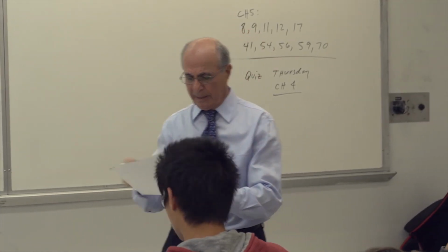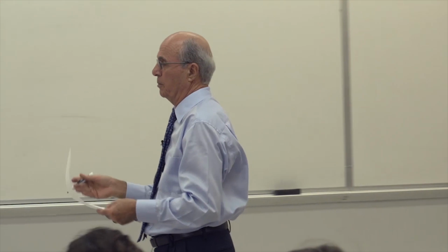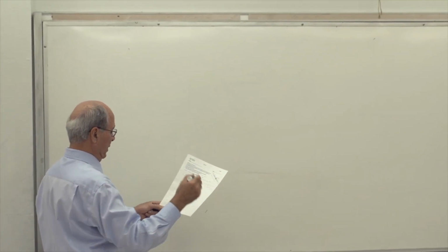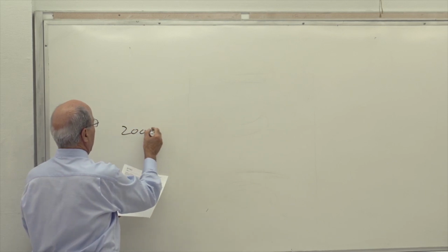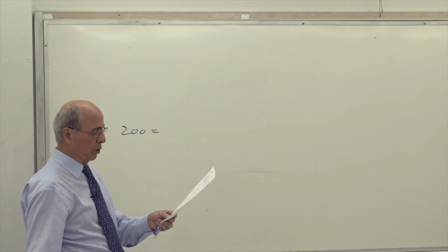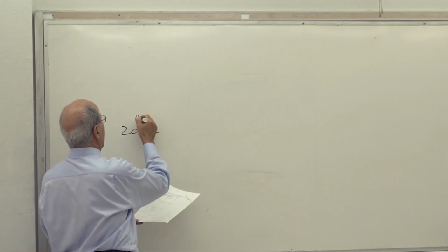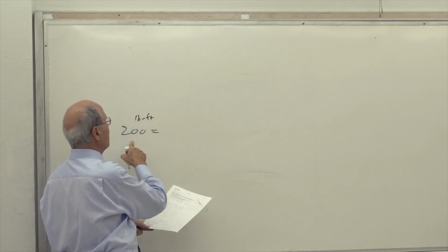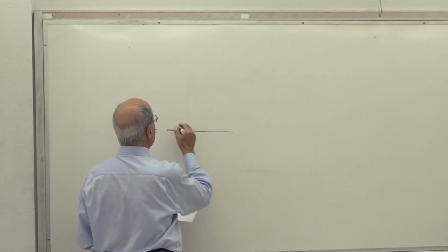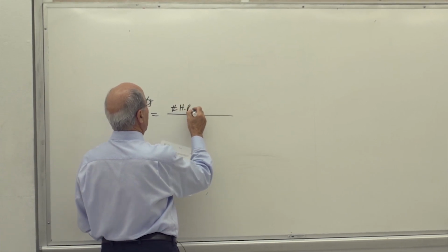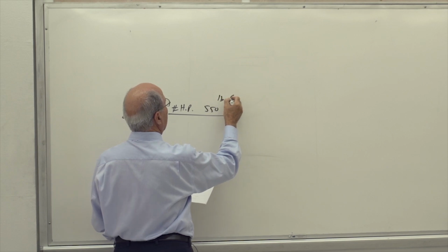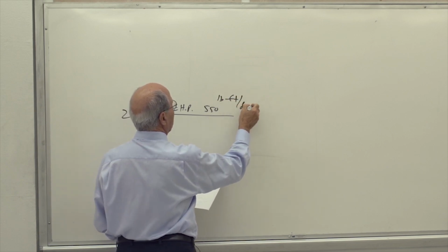And finally, the last one, which many people get correctly because there was nothing to do with this. How many horsepower do we need to create 200 pound-foot of torque? Of course, remember, this is pound-foot. Again, you have to watch out for the unit. Then you don't need to multiply it by 12. Why? Because this was the number of horsepower multiplied by 550. But 550 has a unit, pound-foot per second. Remember that?